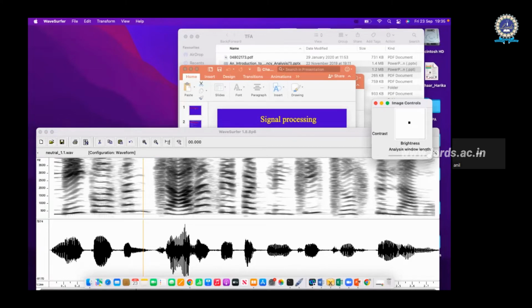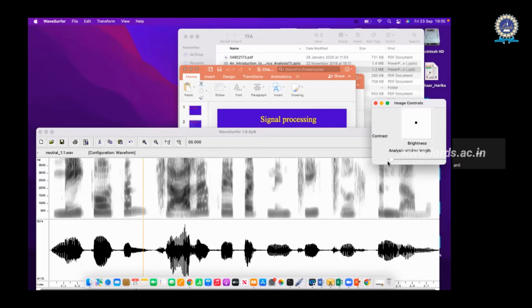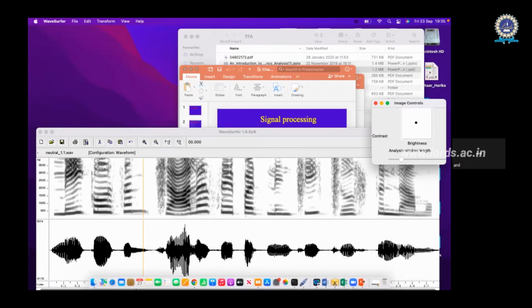You can closely observe the spectrogram. The spectrogram changes. Is it changing? I have taken a very narrow window. You can see the spectrum is quite different. If I take a large window, the spectrogram is getting uniform, kind of the same thing. So your window decides the spectrogram resolution, and within the window, if the signal is stationary, that is perfect. That may not happen all the time. Luckily it happens in speech, that's why it is popular.